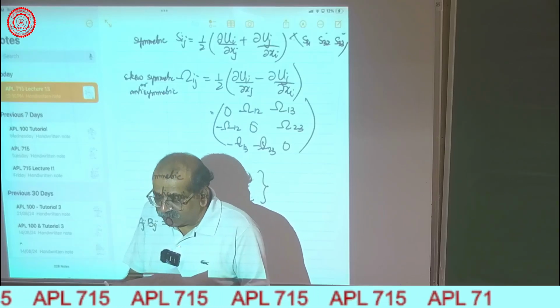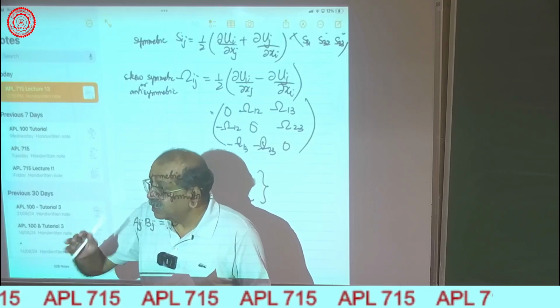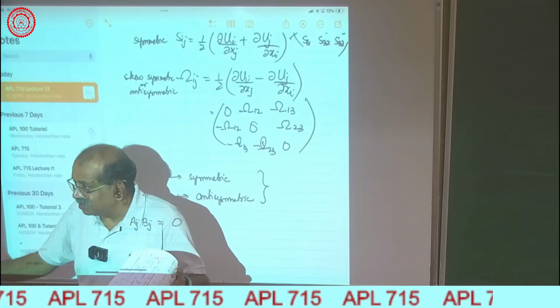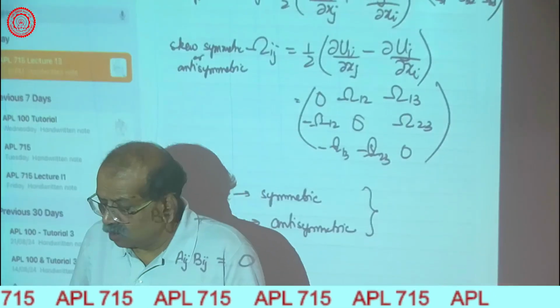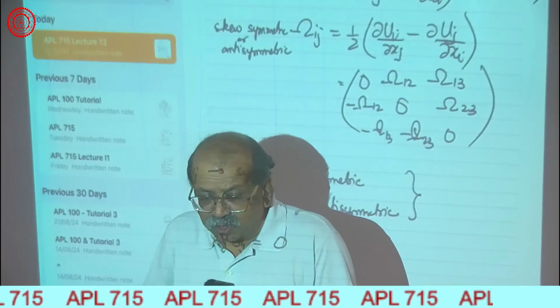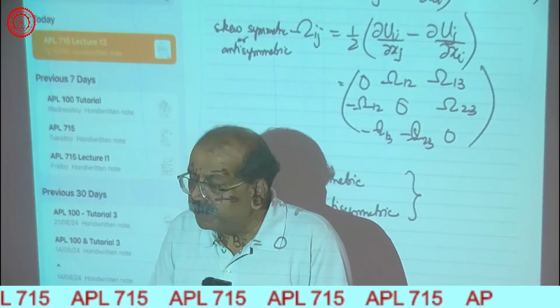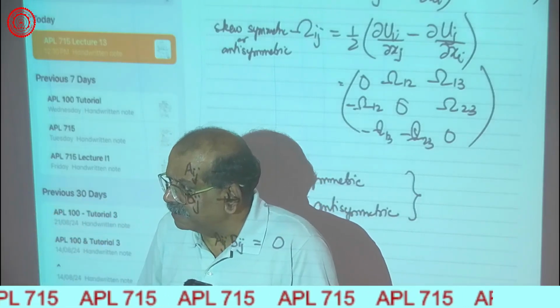So that will become the equation for u_j prime multiplied by u_i prime. Right now you have not averaged anything. It is the equation for the fluctuation. Then you add the two equations. That will give you an equation for partial by partial t of u_i prime u_j prime. Still no averaging has been done.